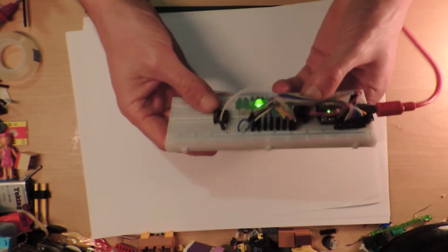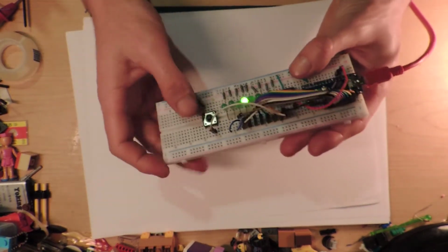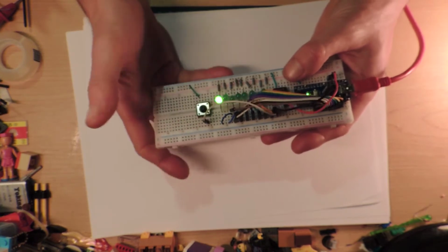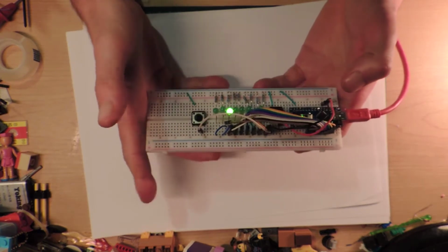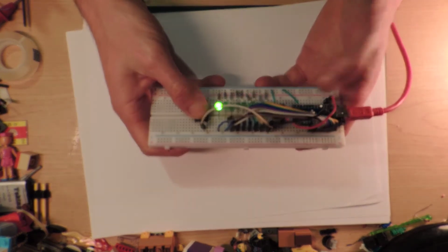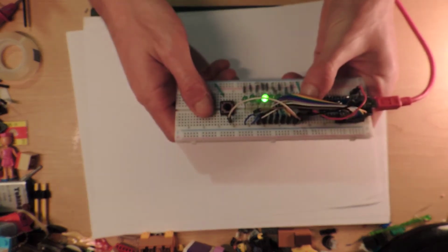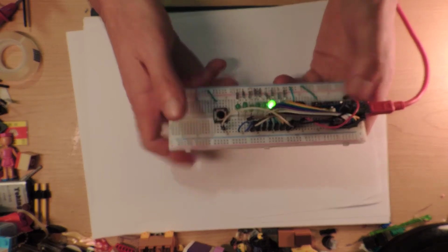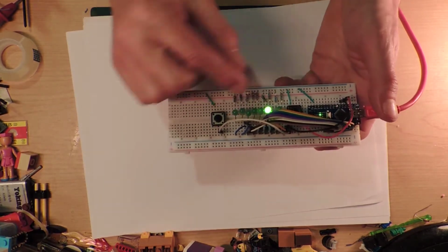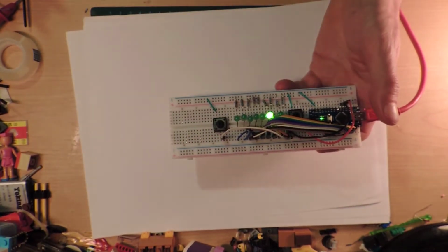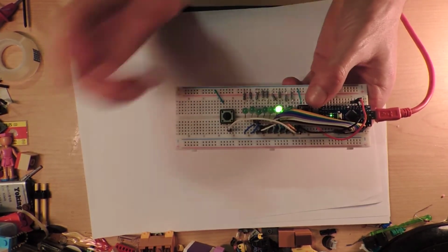I can't remember what the actual term is, but you usually have to debounce things. When you let go of the button or press it down, it will actually vibrate. So when I let go there, sometimes it will shift along. It won't do it as much as it could because I've coded it in a certain way. When I let go of the button it vibrates a couple of times and knocks back down again, creating a contact very briefly, but enough to trick this thing into thinking that the button was pressed again very quickly.